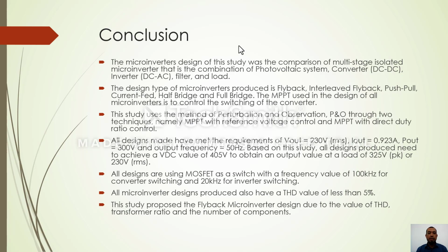Conclusion. The microinverter design of this study was a comparison of multi-stage isolated microinverters, that is the combination of photovoltaic system, converter, inverter, filter, and load. The design types of microinverters produced are flyback, interleaved flyback, push-pull, current-fed, half-bridge, and full-bridge.